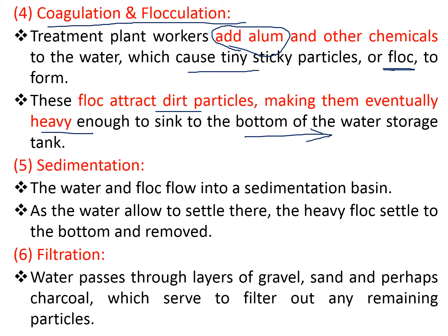So these are the two processes, coagulation and flocculation. Coagulation is nothing but the addition of coagulant, and that is generally done at very high speed. That's why it is also called fast mixing. In flocculation, the speed of the stirrer is adjusted to low speed, because we are giving time for all the coagulants to react and to form the flock. So generally coagulation is fast mixing and flocculation is slow mixing.